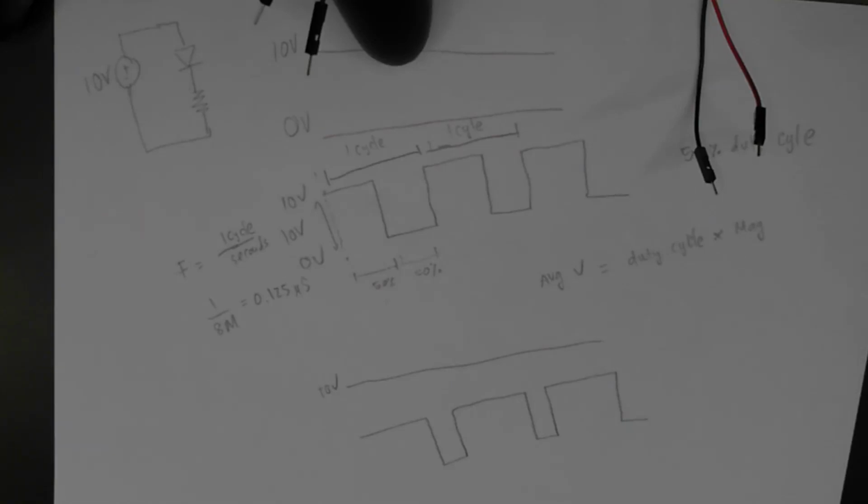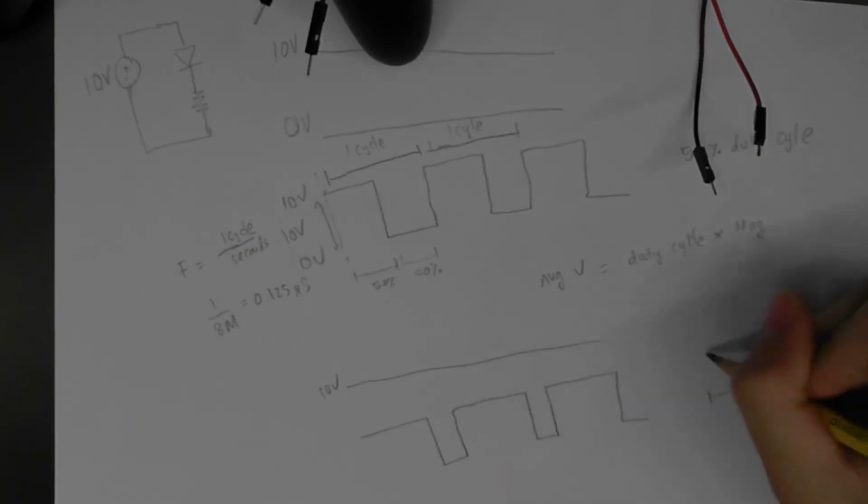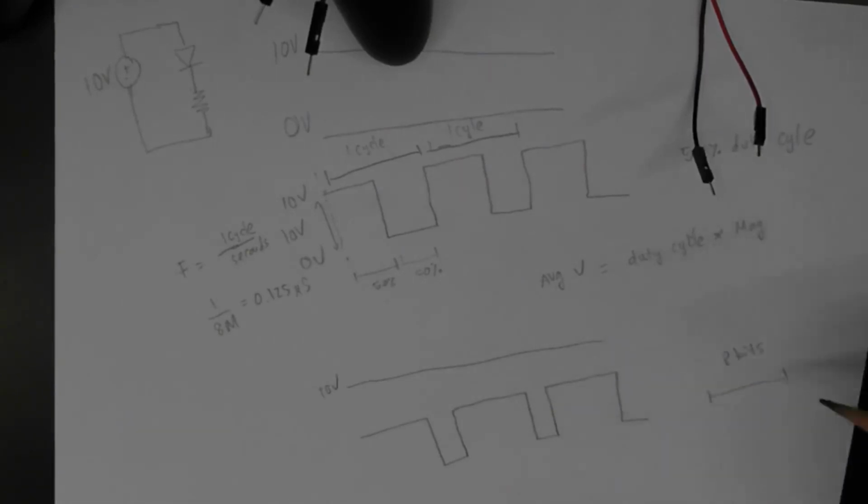To send out these signals using Arduino, in the software you have a register where you put in a value, and it will convert that value into the PWM signal on your output. These registers are 8 bits, so using 8 bits you can have a value between 0 and 255, corresponding to 0% duty cycle and 100% duty cycle.